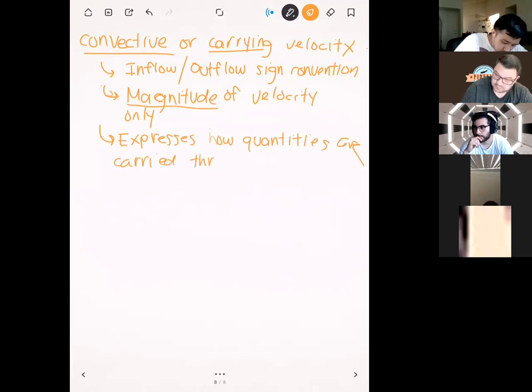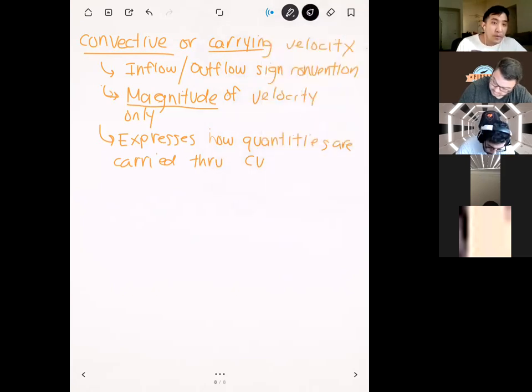And so if you think about it, we had this U dot N term for our conservation of mass. In conservation of mass, this U dot N expressed how mass was carried through our system, and that's a pretty intuitive thing. But in this particular case, momentum can also be carried into our system and out through our system. It's a weird concept, because you can't pick up a bundle of momentum and carry it across into the wilderness or something like that.